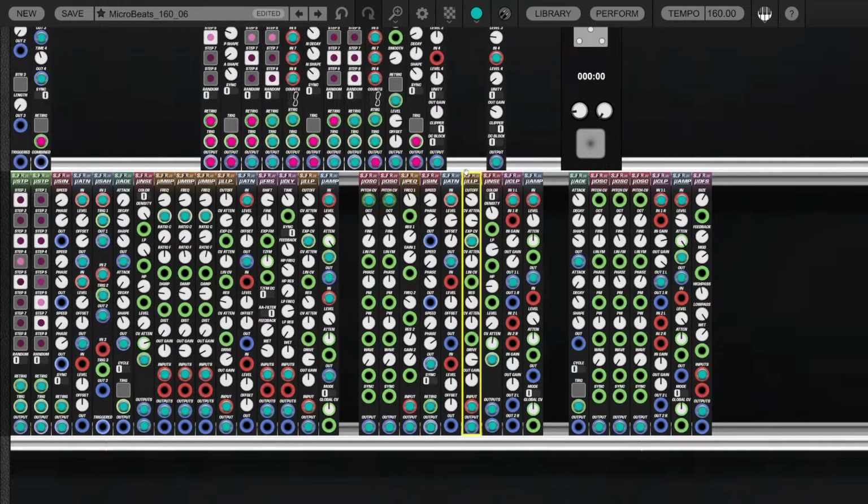This signal goes into a low pass filter and then into a clipper. The low pass filter is modulated by some sine LFO combination that is attenuated. Yeah, only that. We drive the low pass filter, it's a nonlinear filter, to add some harmonics. And then we go into the clipper. And the input to the clipper is mixed with some noise that is also modulated by a sine LFO, which gives us this breaking up effect of the bass line every now and then.